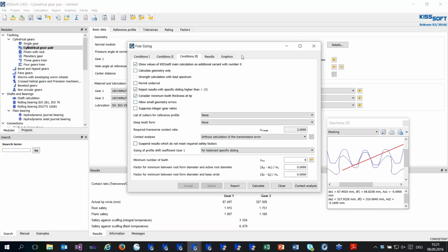We have these things here mainly for special cases, for example, power tools. In power tools, hand drill machines, for example, you have very often a gear with a pinion of 4 teeth, and if you would like to have a solution in that range, you always get undercut and other nice things, so you have to admit such solutions. Then you pick out what looks like a nice solution. You have to refine it later in the basic data.